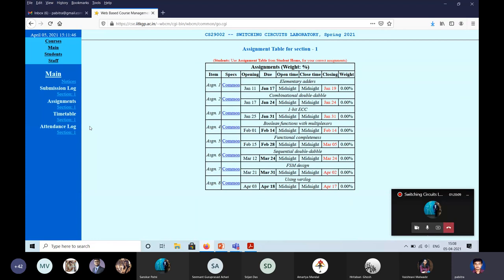So first you have to install iVerilog. By the way, this iVerilog is a free Verilog. It doesn't have all the functionalities of Verilog, of the synthesis steps specifically. The commercial ones are more costly. So this iVerilog is free, and the first thing you have to do is write a .v file, which is a Verilog file. So using Notepad or something, you write a .v, which are these programs we have discussed.